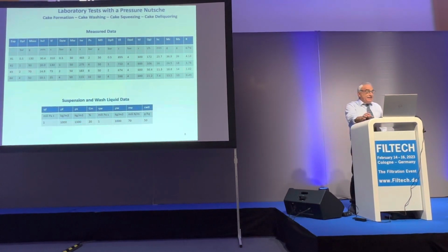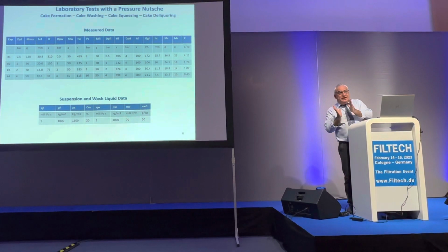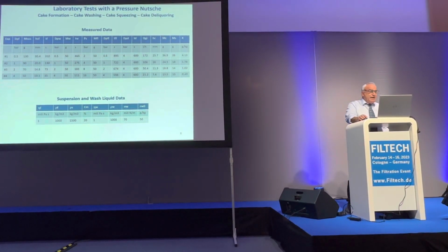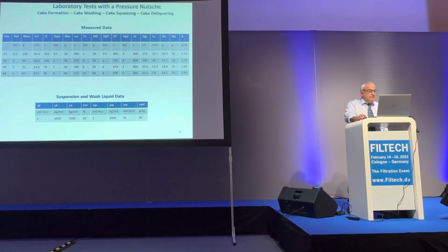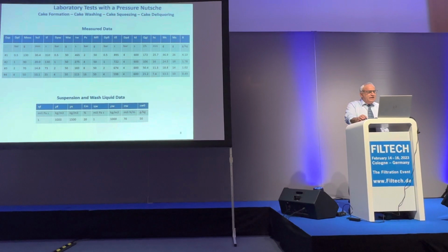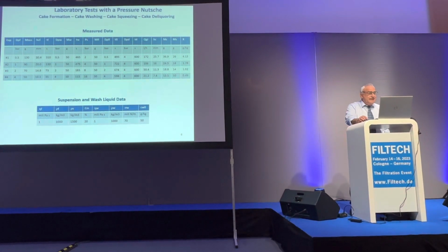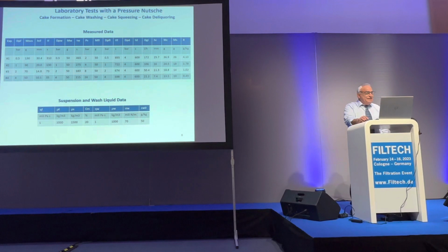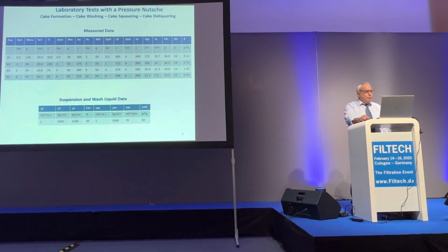And then we make a flow-through test to get the permeability of the squeezed cake, with a definite amount of liquid, in this case wash liquid, and a definite pressure difference. Then that is the time needed for this given liquid amount above the cake to go through the cake.